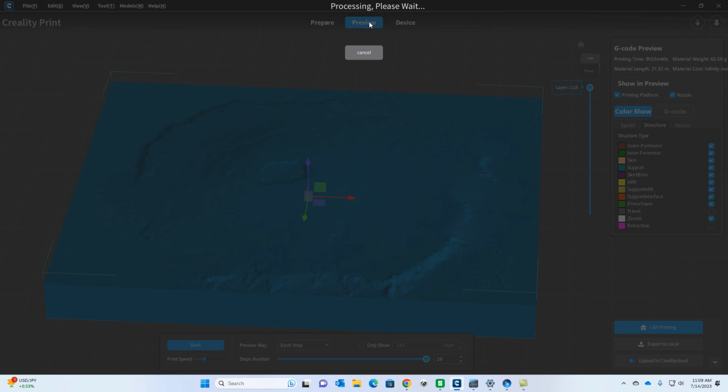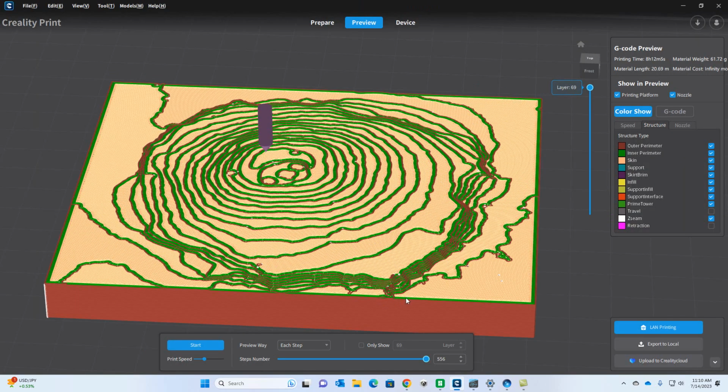And then when we click on the preview, you can also notice that the base itself is a lot thicker. This will take a lot of printing. And if you have dense infill, then you're really going to be using a lot of plastic, and there's not going to be that much in terms of layer density on the top.